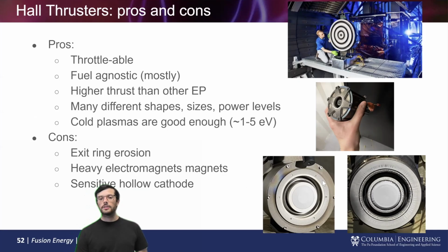When you have an ion, if you remember back to our cross section, an ion gets born. Basically, it loses an electron pretty far inside the channel. It will most likely go straight out, but it could go out at a slight angle, and if it goes at a slight angle, it might run into something. So in the places where those ions could run into a surface, we use this very strong ceramic. What that's doing is trying to limit sputtering. Remember sputtering from a few slides ago? That's when an ion runs into a material and breaks off some chunks. These ceramics are basically very resistant to that.